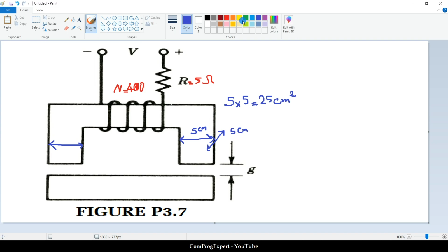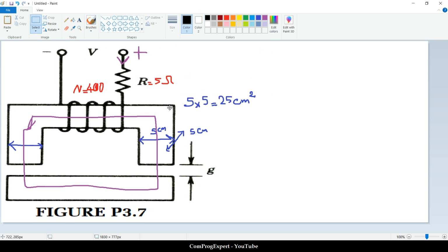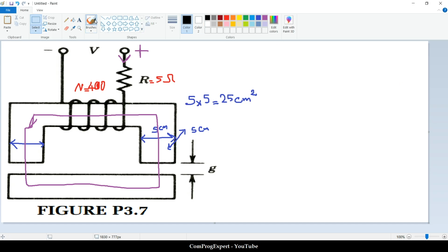Here in this structure, this is the positive terminal of the DC supply. This is the direction of the current in the coil, and we will have this field generated by this coil. If I plot this flux line in the middle of the structure, okay, we can use this equation to calculate the required value for the coil current. Integral of H dot dl is equal to Ni.